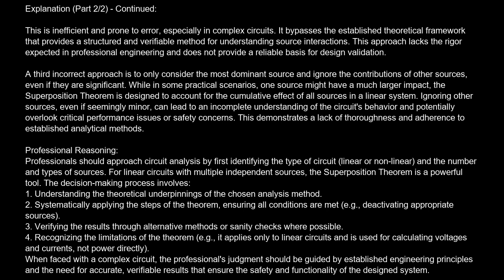A third incorrect approach is to only consider the most dominant source and ignore the contributions of other sources, even if they are significant. While in some practical scenarios, one source might have a much larger impact, the superposition theorem is designed to account for the cumulative effect of all sources in a linear system. Ignoring other sources, even if seemingly minor, can lead to an incomplete understanding of the circuit's behavior and potentially overlook critical performance issues or safety concerns. This demonstrates a lack of thoroughness and adherence to established analytical methods.